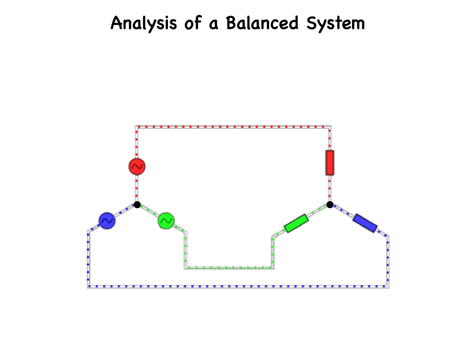In this balanced three-phase YY system, the source is an ABC sequence set of voltages with VAN equal to 120 at 40 degrees volts RMS. Since the source voltages are balanced, the other voltages are plus and minus 120 degrees apart from VAN with the same magnitude. The per phase impedance of the Y-connected load is 10 plus j8 ohms.